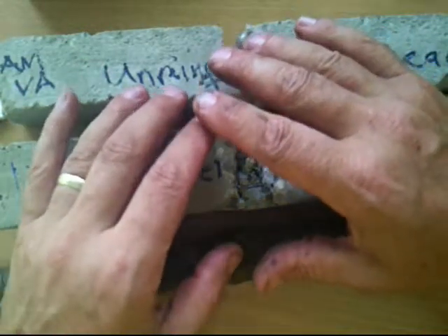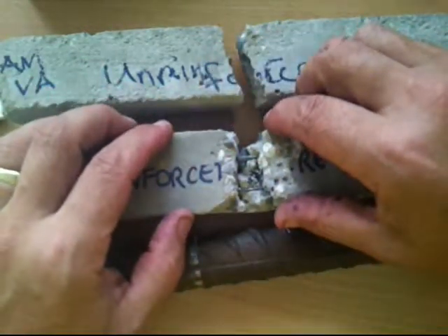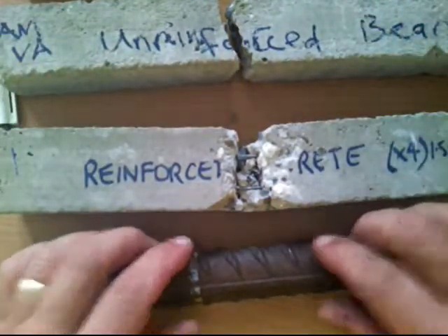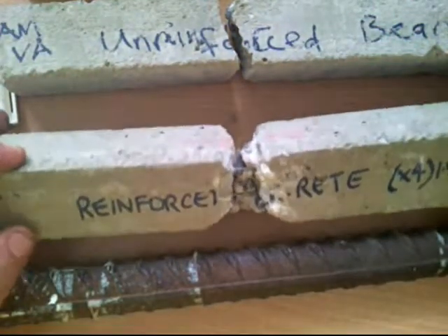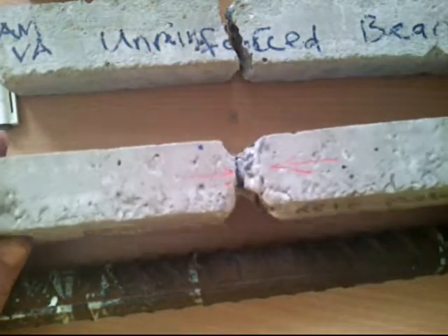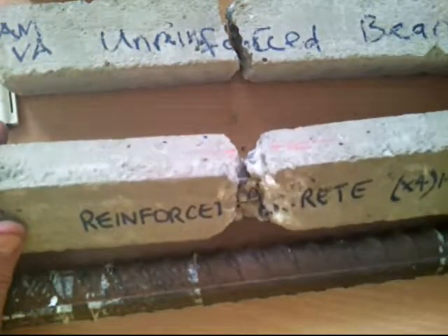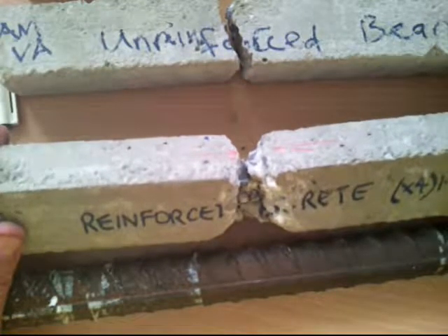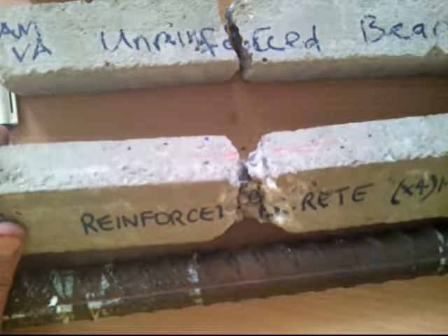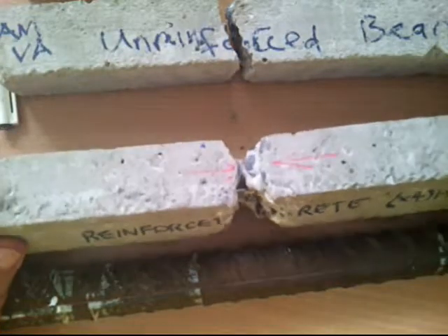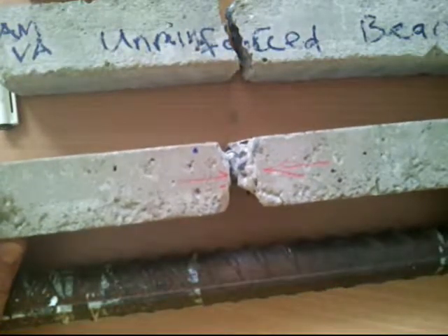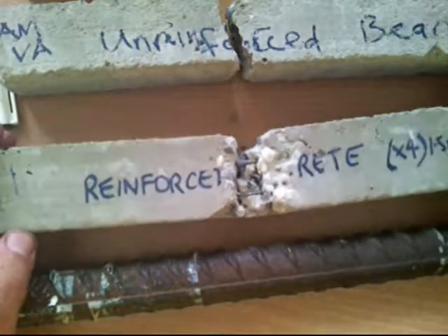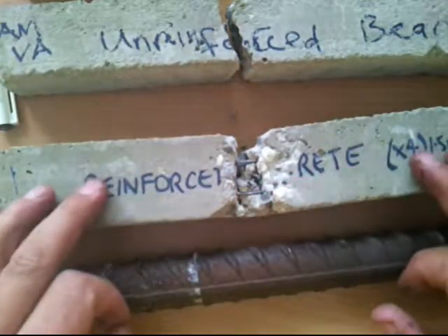Lay a mesh down and pour the concrete over the mesh, let it harden and solidify, and you get quite a strong structure. But in some cases, we don't want to have simply a strong structure. We need a fairly light structure. So if this was a beam supporting, say, a large span of a bridge, then we would want to reduce the size of the beam as much as possible, and at the same time be able to put it into place with a minimum of fuss.